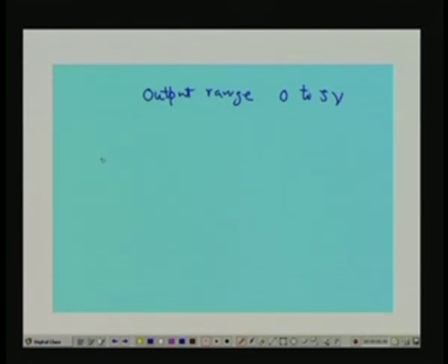And we need, you see, basically one Wheatstone bridge along with the instrumentation amplifier. The Wheatstone bridge is necessary to give an output of 0 volt at 75 degree centigrade, and the output of the Wheatstone bridge will be very small, and hence an instrumentation amplifier is necessary. Now, we have proposed the following circuit, right. Let us look at the circuit.